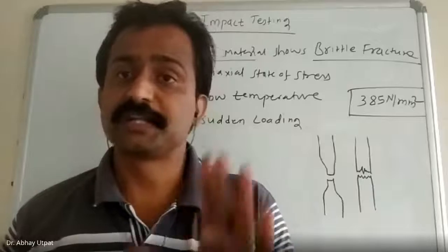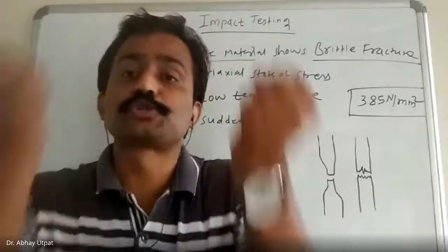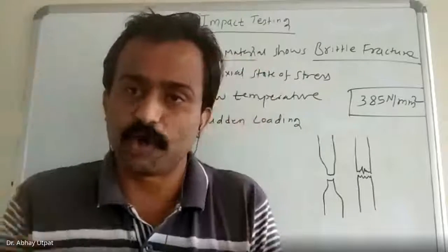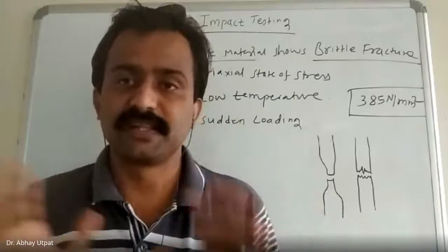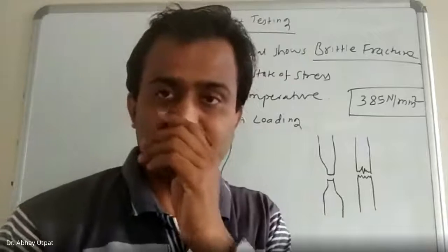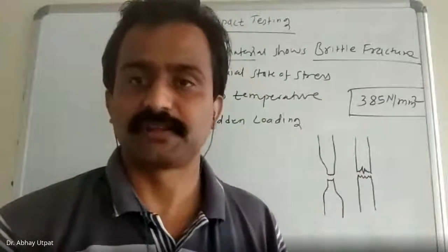Now we are understanding the meaning of the word impact strength. Impact strength means good shock absorbing strength, which can sustain the shocks, which is having good toughness. Very simple. So which property is measured in the impact test? Toughness, energy absorbed prior to fracture.